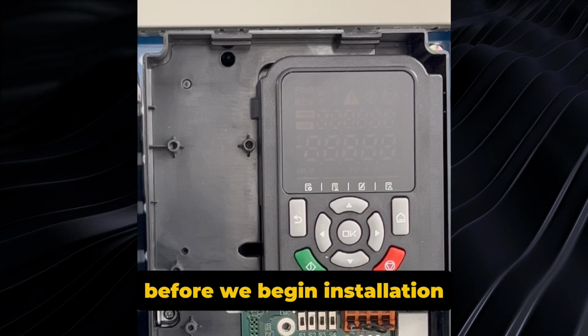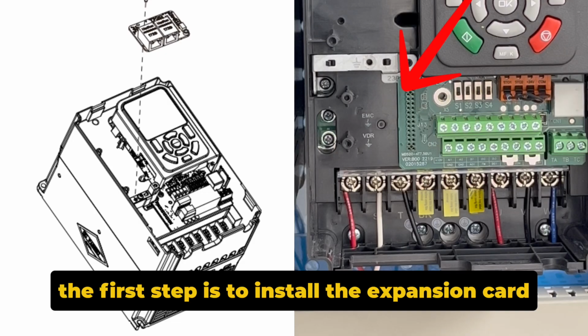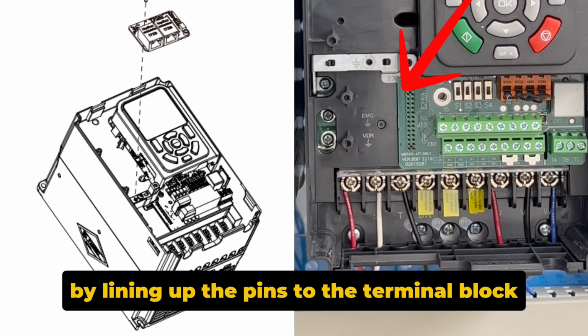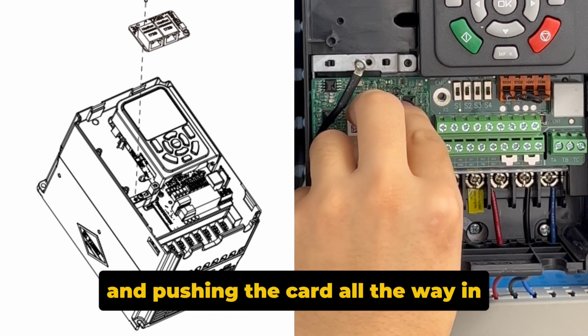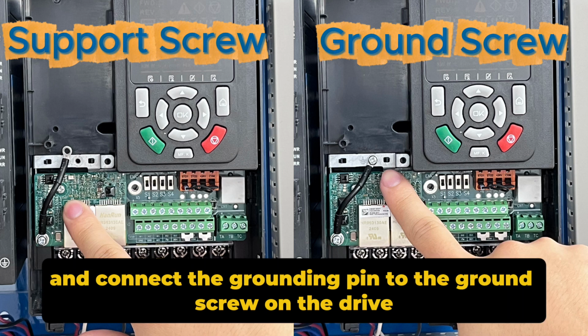Before we begin installation, make sure the drive is fully powered off for safety. The first step is to install the expansion card by lining up the pins to the terminal block and pushing the card all the way in as pictured. Next, screw in the support screw and connect the grounding pin to the ground screw on the drive.